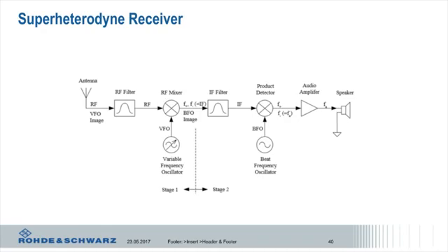So if you look at it, there's that same sort of stuff on the left, but now I have an RF filter added to it. That's to first off limit the bandwidth of my spectrum so I know what the noise bandwidth I'm working in. But it's also to reject other signals coming from other things, cell phones, cars, garage door openers that I don't want. That comes to a lower frequency, which we call an IF. Then that IF signal is filtered again, and then it's going to be further reduced to a lower frequency and then processed. So in the old world, things were just audio, but obviously this would be something more like data today.